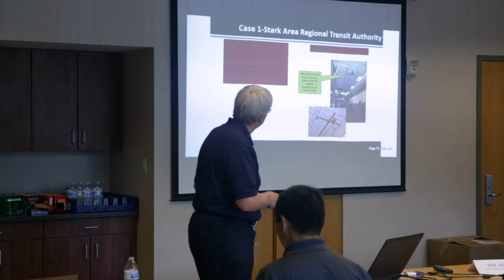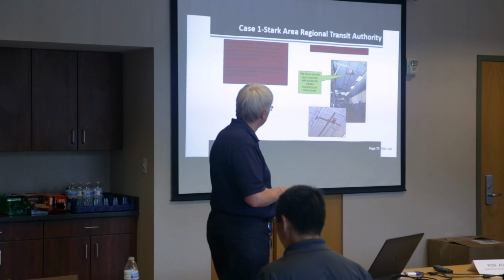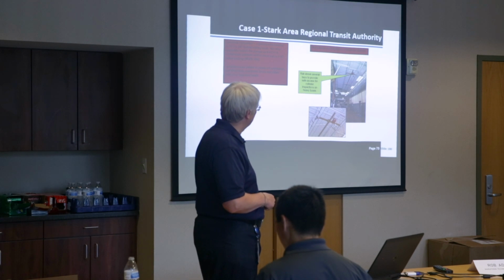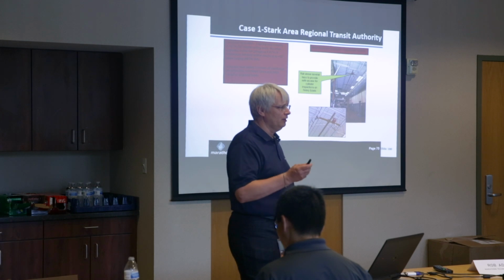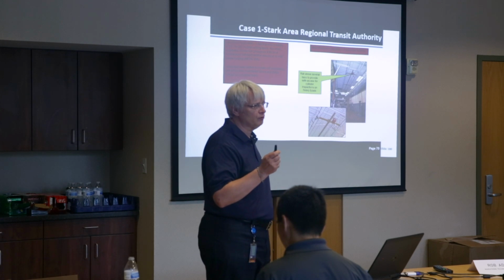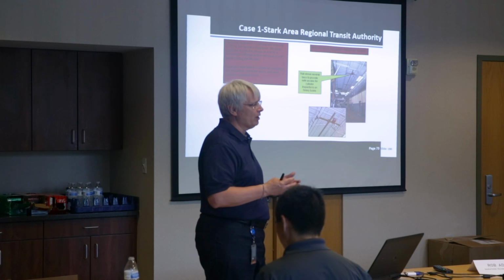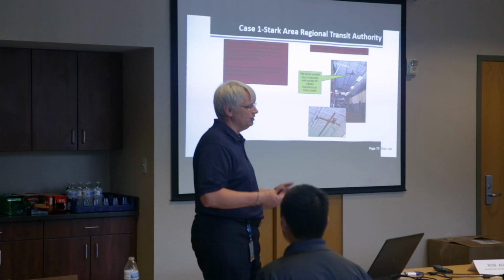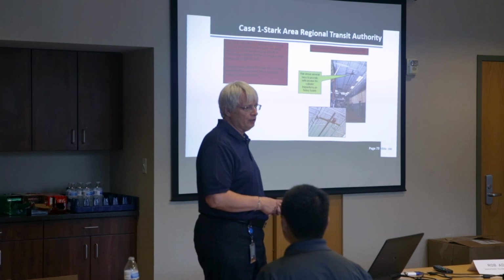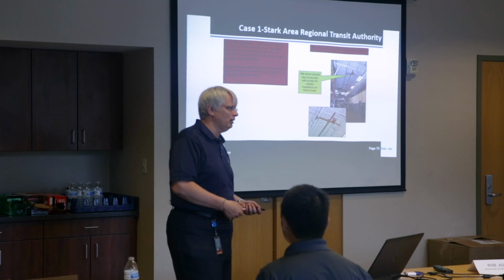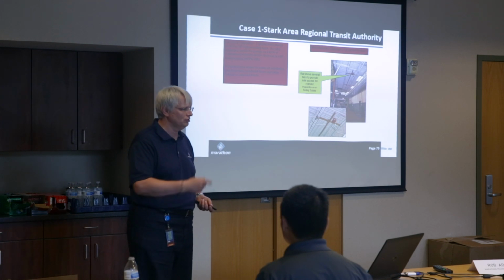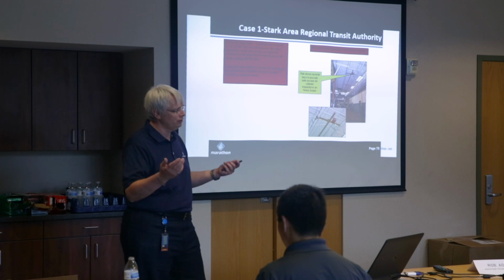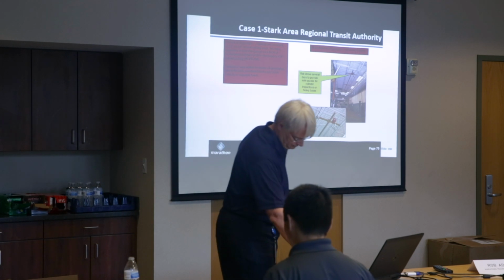They did add a generator to power the ventilation, gas detection, overhead doors, and the other safety critical loads. So they have a rail up here in one of their bays, and again, that's for purposes of safe cylinder inspection on the roofs of the buses. Both hydrogen and CNG buses have the tankage on the roofs, so you're going to need to get up there for that. And for any of you folks that are dealing with hybrid buses or electric buses, same thing. So you'll need that same kind of system for them.